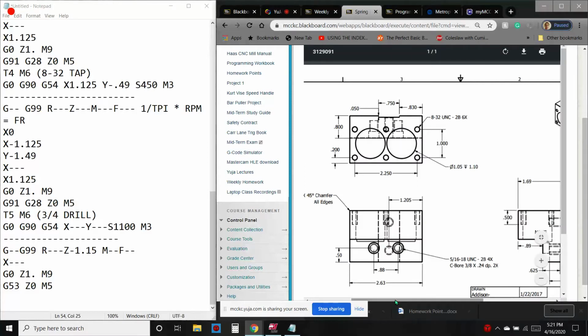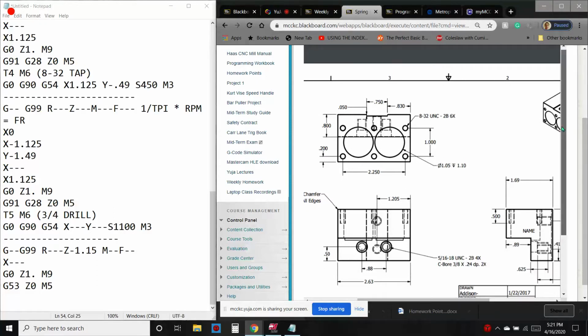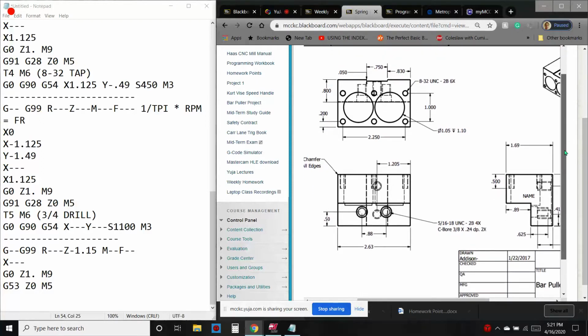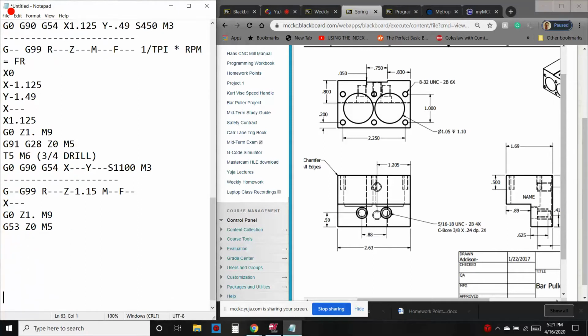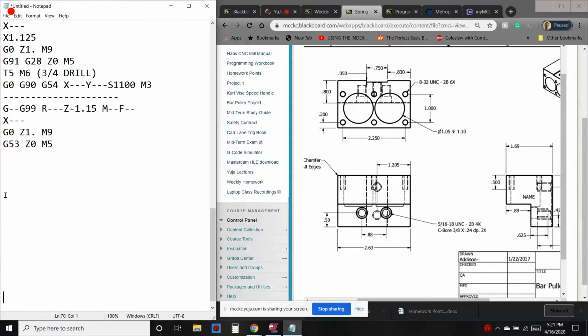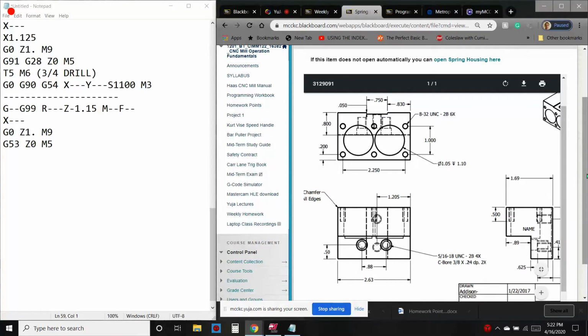It's a lot easier with Mastercam because you basically click the helix bore tool path and a couple mouse clicks and you're done. So this will be a little bit more involved, but you'll get a good gist of how this is going to work. So let me enter this up, and we'll just start our next tool. And since these bores are 1 inch, I'm going to say the logical thing to do would be to use a 3/4 inch end mill, like a 3/4 inch finish end mill.